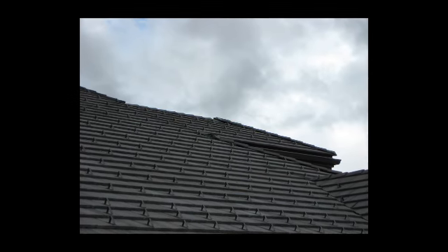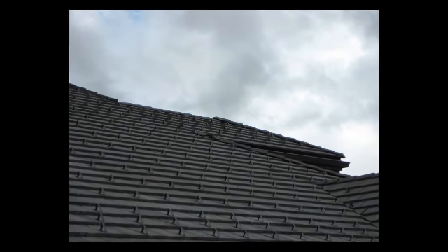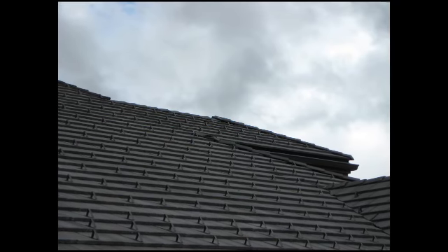I also found that they use snow retention on the roof to hold the snow so that they could use it as an insulated blanket. I noticed that it wasn't just at the eave, but it was on the entire roof from eave to ridge. And that's because they said they needed to have it as a blanket on the whole roof. And they didn't want to introduce force loads of the snow and ice moving.